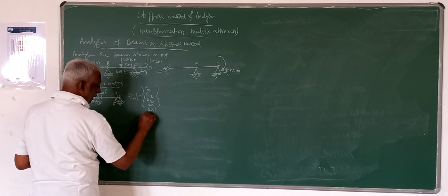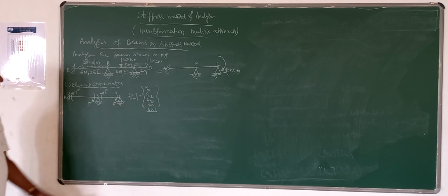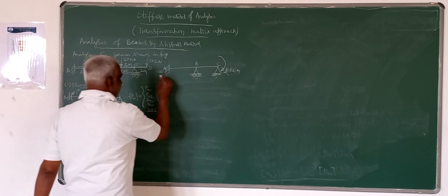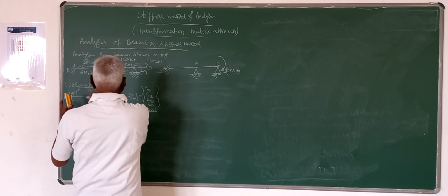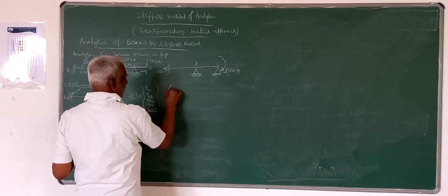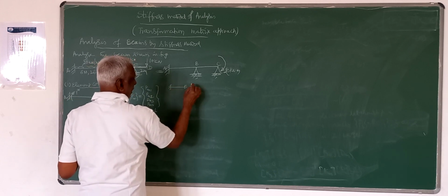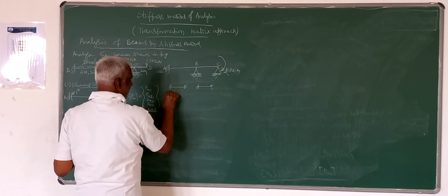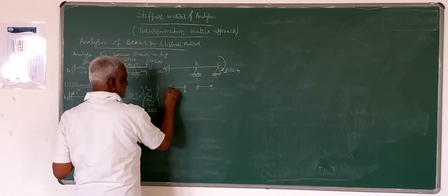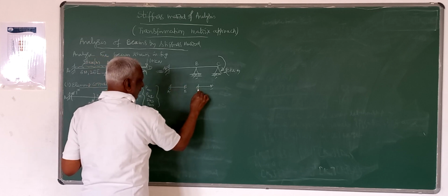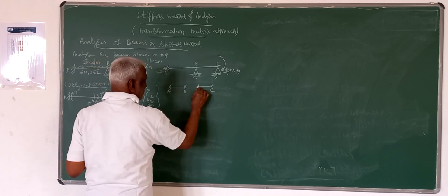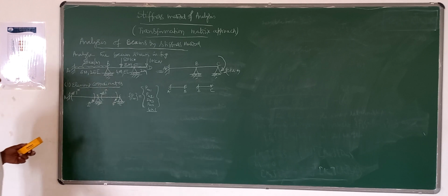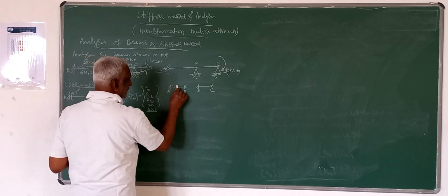It's a 4x1 matrix. This we have to determine. And then we have to assume each of these members to be fixed at the joints, at the ends, like this. Member AB is assumed to be fixed at A and B. Likewise, member BC is also assumed to be fixed at B and C, and due to whatever loading is there,